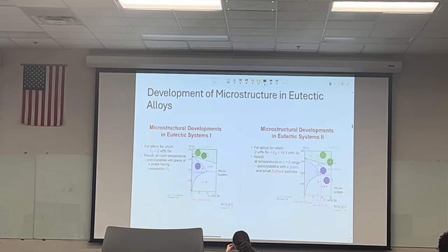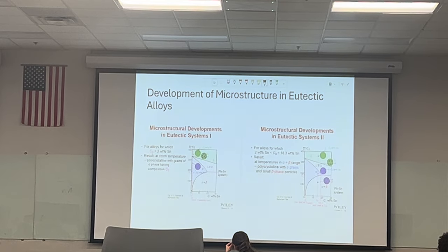So the first case applies to compositions ranging from a pure component to the maximum solid solubility of that component at room temperature. And essentially it explains what happens when you have an almost pure metal that cools from a liquid state into a solid state. So I believe that's what this image here on the left is basically saying, or how you would read it.